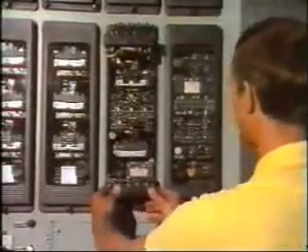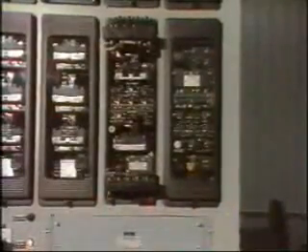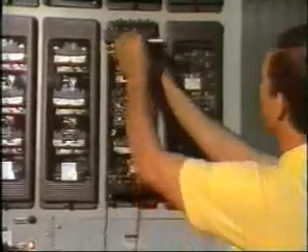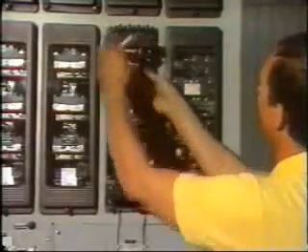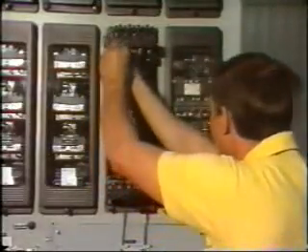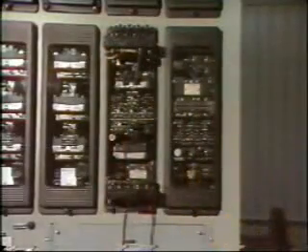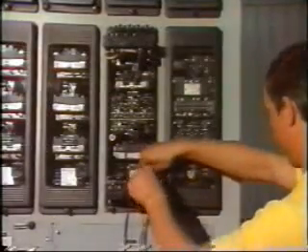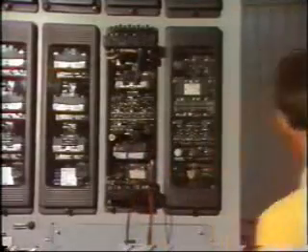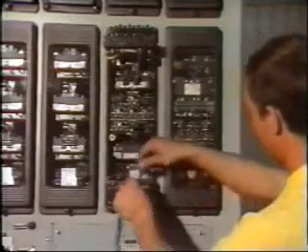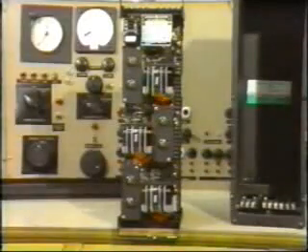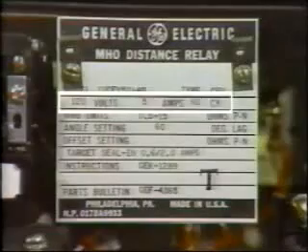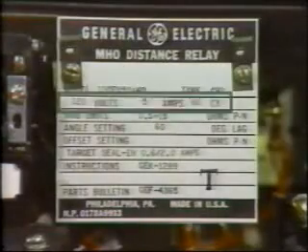We already know from earlier tapes that sensing information is provided to the protection system by coupling the relay to the load circuit through instrument transformers. Current transformers, CTs, and voltage transformers, VTs, step down the power system current and voltage to safe working levels. This provides significant protection to the relay and also to personnel working on the protection equipment. Low voltage and current also permit the relay equipment to be made small and precise. Typically, the relay will work at, say, 5 amps and 120 volts.